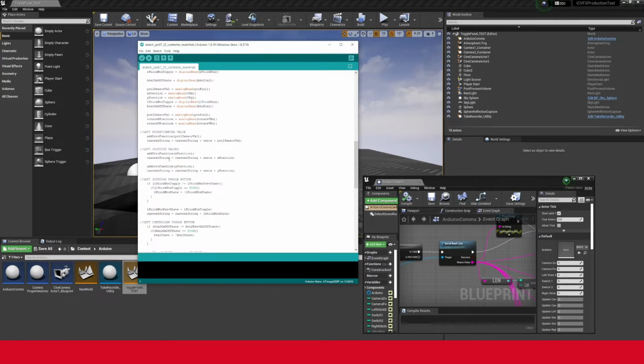Previously, we would have just printed straight to the command line, appended that inside of the print process, and then created a new line to reset it. I found that if there was a bit of a desynchronization between the Arduino commands being sent and UE4 reading them, sometimes it would truncate that line, therefore causing a lot of different problems.